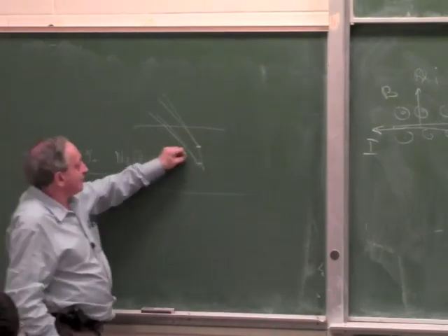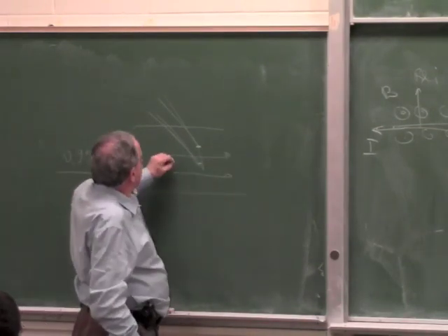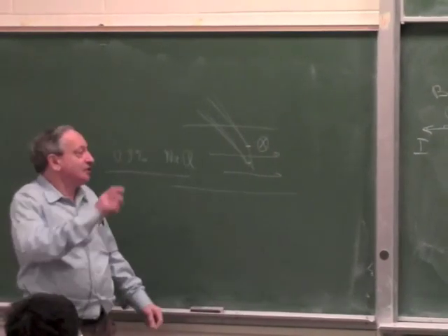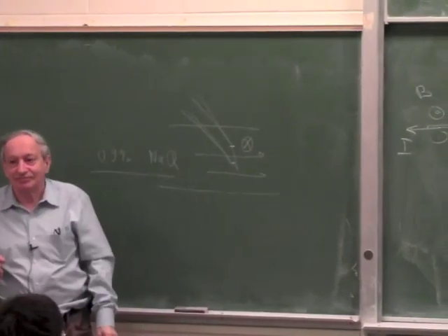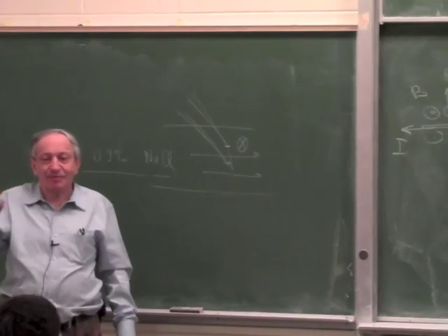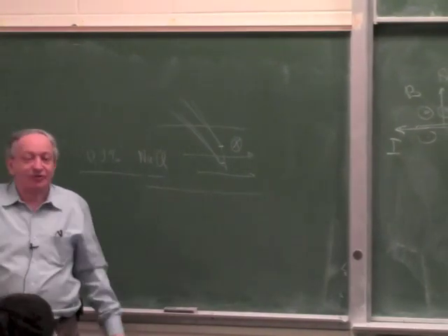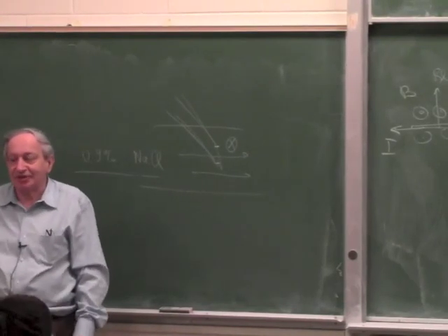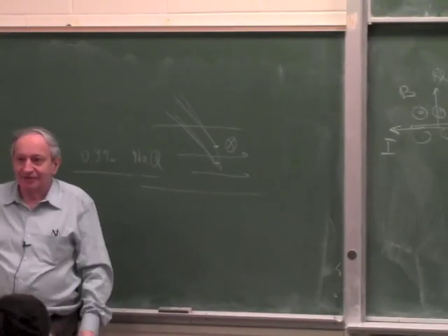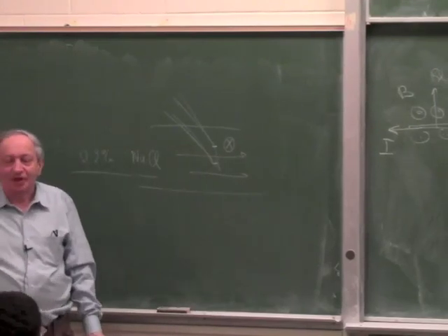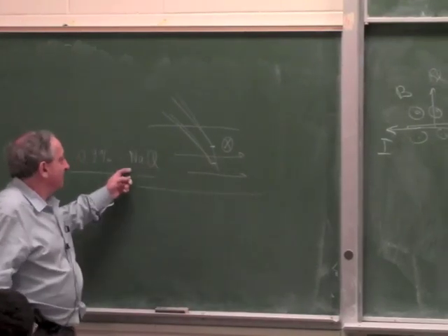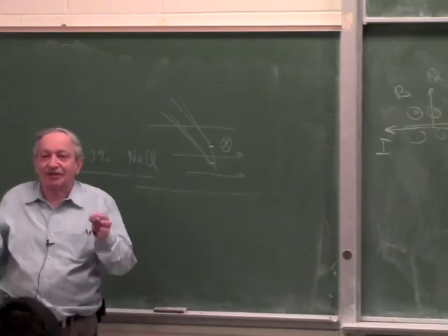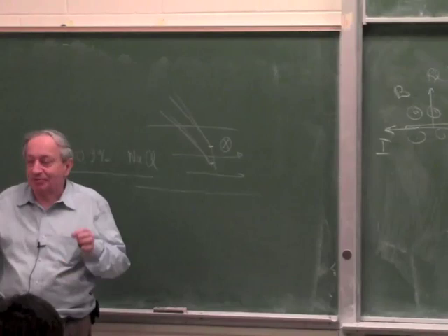So if the blood is flowing in a magnetic field, you'll get a voltage, and the voltage is completely linear with velocity. So maybe 5 of you suggested that in the first assignment, how to measure blood velocity, which is quite elegant. Because the field doesn't have to be high. Remember, it's a low frequency signal. The field doesn't have to be like an MRI machine.